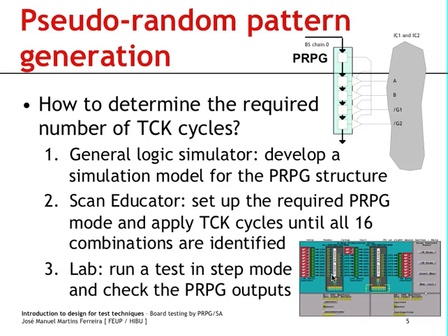Alternatively, however, we can use the Scan Educator package, which is an old simulation tool developed by Texas Instruments, and it was meant to explain the operation of the boundary scan logic inside these devices, and so it really offers an exact replica of the boundary scan architecture that is present in these components. It's an excellent utility, the only problem being that it is so old that you will actually require something like the DOS box in order to be able to run it in Windows.